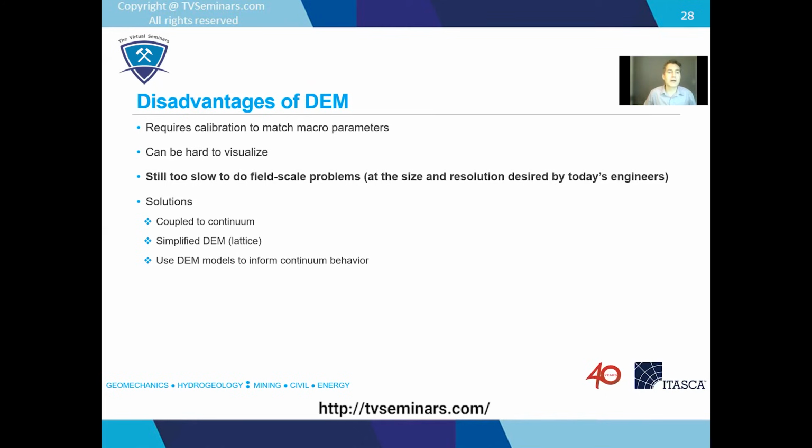So what do we do? There are a couple of possible solutions here. We can take the discontinuum model and couple it to a continuum model, so we're only putting in discontinua in the region of interest. Another possible solution is to try and simplify the formulation. I'll show an example of that. And then the third sub-bullet here is it's possible to run a bunch of discrete element models to get a feel for the behavior that you're looking for, and then encode that into, again, a sort of simplified version of this thing.